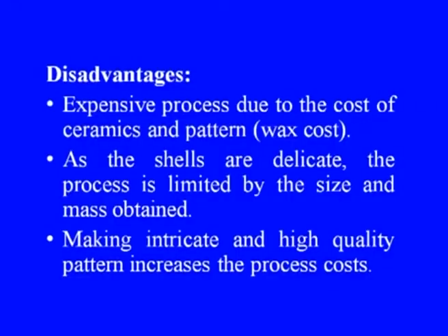This process produces castings with excellent surface finish. Now, let us see a few disadvantages of the process as well. The process is expensive due to the cost of ceramics and the pattern, which is made of wax. As the shells are delicate, the process is limited by the size and mass obtained. Making intricate and high quality patterns increases the process cost.